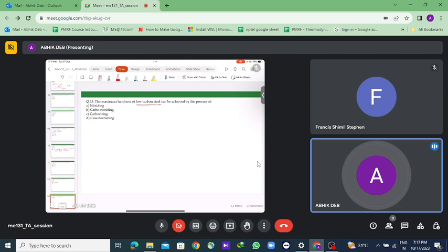Sir, austenitic? No, this is done. That is a specific process with a specific condition. For nitriding, the temperature needs to be in the range of around 500 to 550 degrees. So this is heated up to the ferritic stage. If we heat up to the austenitic stage,